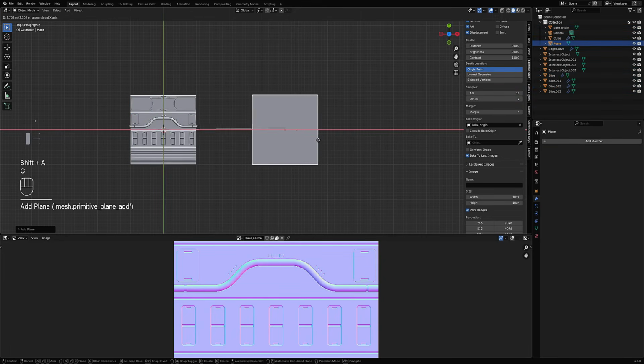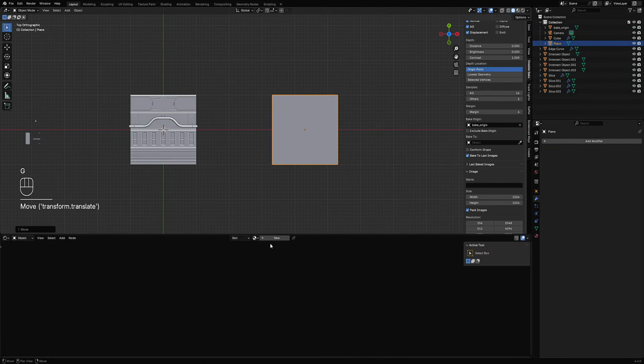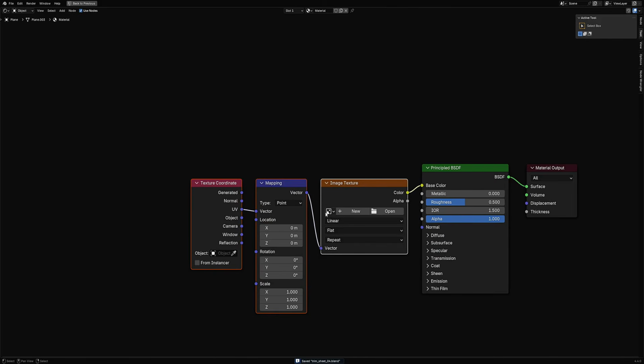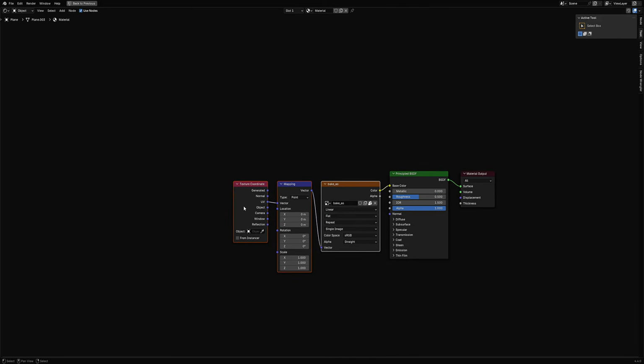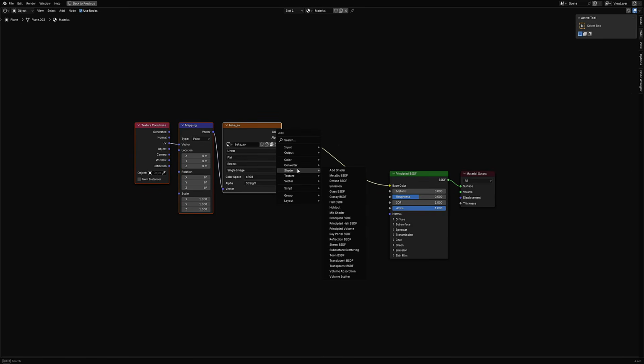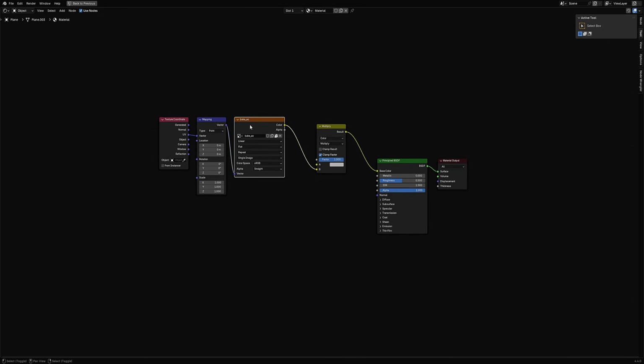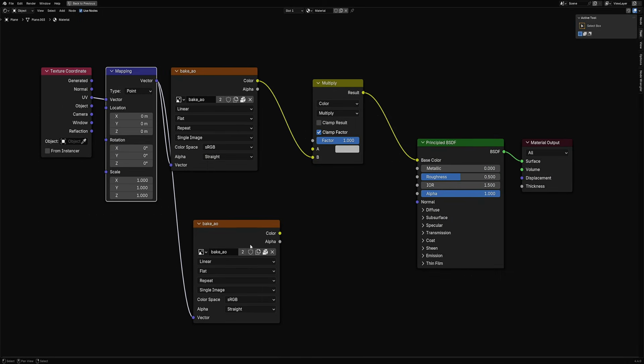Okay, and let's create a material for that. New... oh no, save the file first. Control T. For diffuse, let's just use AO as a mix for the color, mix color. So the A is where your texture is supposed to go, and then set our normal map.